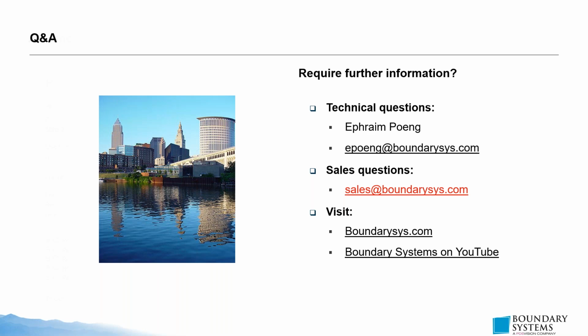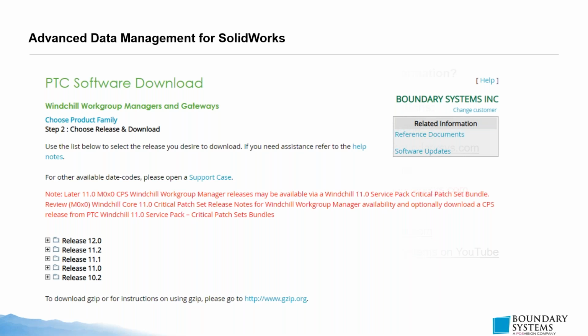Right, so getting into the actual topic of today, I want to start off by again explaining what a Workgroup Manager is. Workgroup Manager is basically a tool used to integrate the Windchill PLM system with the CAD tool Solidworks. So that's basically what it does. And the actual software component of it can be downloaded from the PTC website. You just search for the version that relates to your Windchill version, and you simply install that version and then link it to your Solidworks. Or obviously, when you get to the demo, I'll show you how you actually go about doing that.